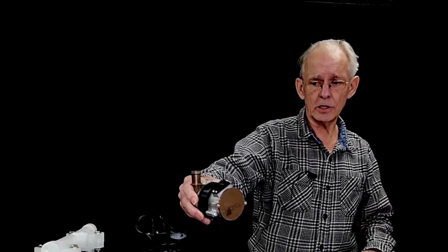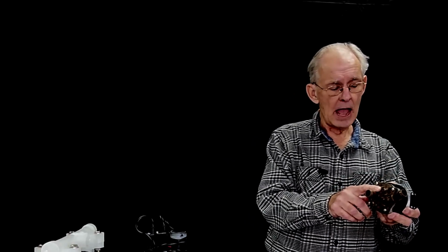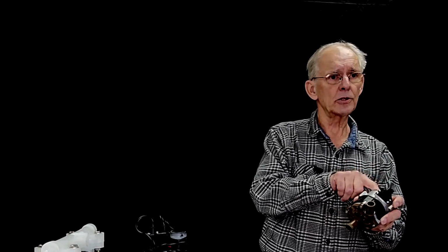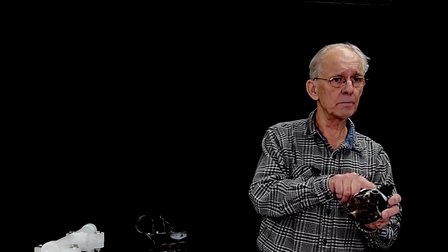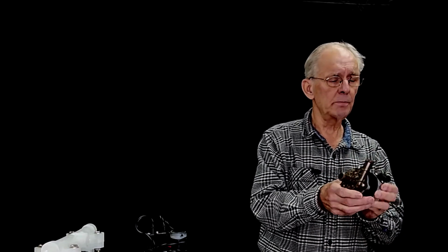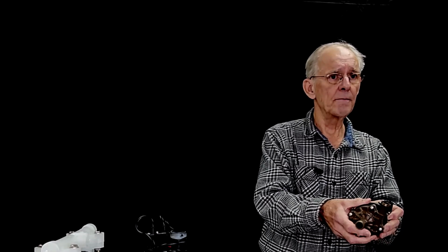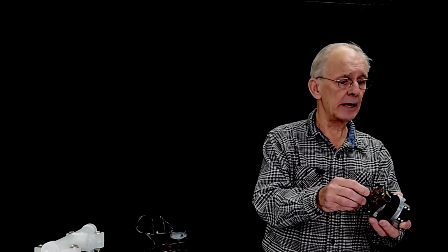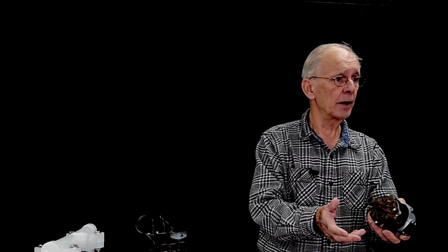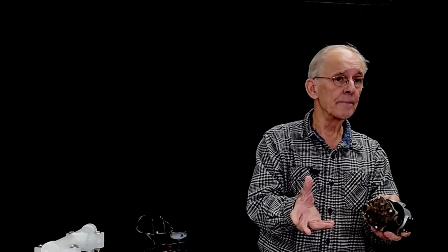This little guy here is a centrifugal pump, and what I didn't mention is this one also has a brushless DC motor driving it, which is variable speed. And this pump is also submersible. This is an automotive pump. This can be put in a tank underwater and used as a submersible pump, or it can be external with hoses attached and run that way. And again, because it's variable speed, it's got a very wide range of flows. Centrifugal pumps are the most widely used pumps because they're very, very, very flexible.